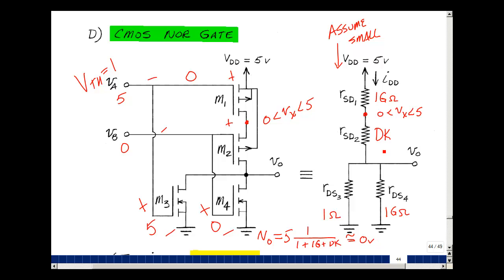It turned out here that the don't know became a don't care. And for commercial logic gates, that'll be the case. But if you make up your own logic gate, that might not be true. Given 5 and 0, the output is low or 0. Let me again erase this and take a look at the last case.